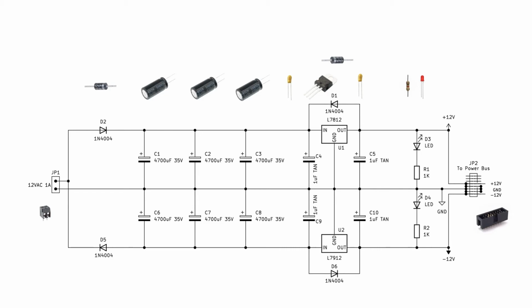On the input side, I will place a PCB screw terminal block. The output side will be connected to a 16-pin IDC header, which will be connected according to the Eurorack standards.